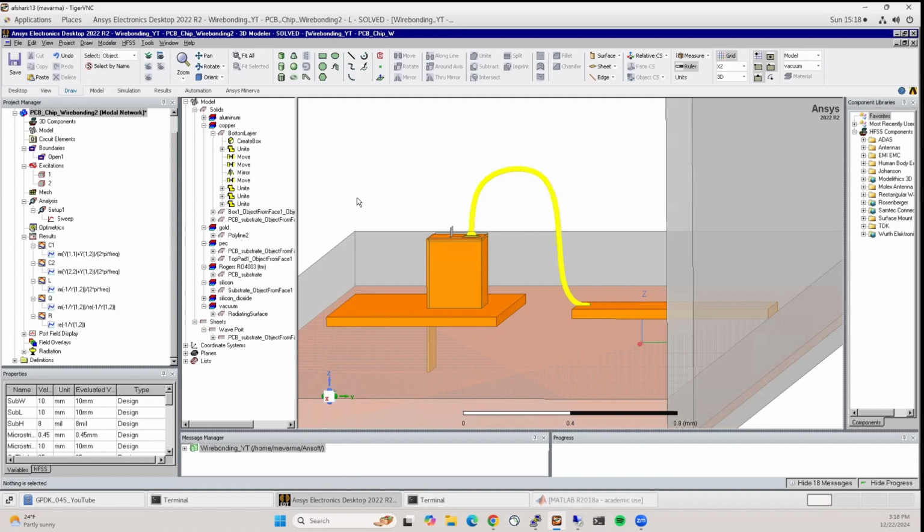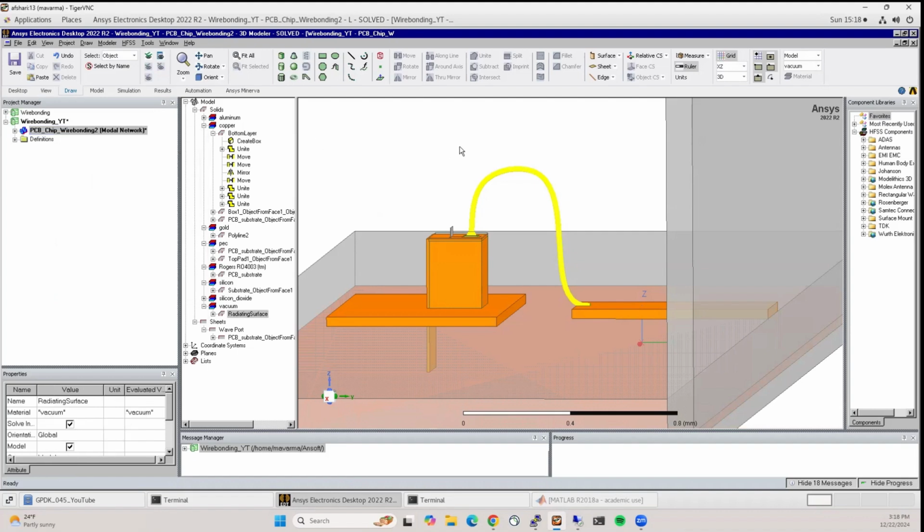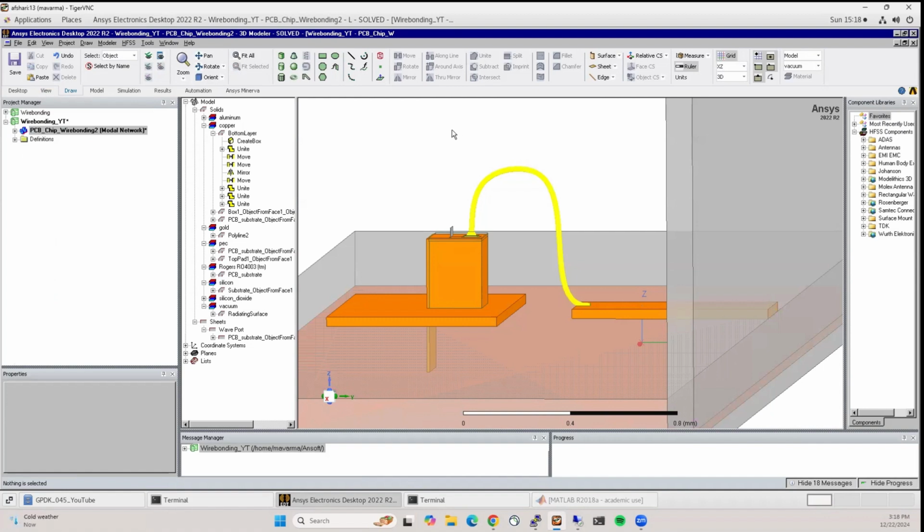I still haven't shown you how to do the capacitances of the pads, so let's quickly do that. All I wanted to show you here is that you have to establish a 3D EM model that faithfully represents the circuit model that you're using to extract these circuit parameters. It doesn't mean that your chip has to have this big piece of metal here. It just means that this is the closest way to approximate that circuit model. You can use more complicated circuit models, but for a first pass hand calculation, this is very good. You can even rely on this empirical model.